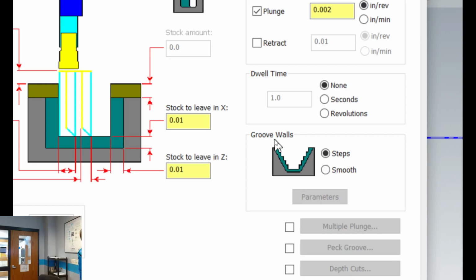Okay, and then when the insert comes in, it's gonna try to clean that out all at once. So if I do have a tapered wall groove, I always leave it on. I put it on smooth, so it creates basically just like the turning. It creates an overlap. So as it roughs it, it'll basically take it all down to here, and it'll rough these out. That way, you get a consistent 10 thou all the way through the finish pass.